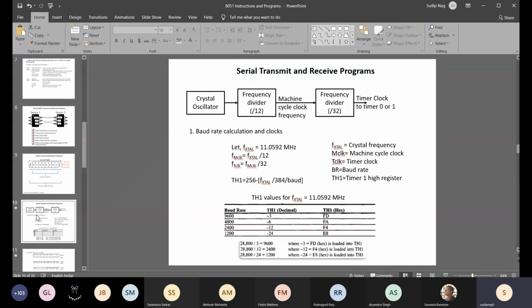So here you can see the crystal oscillator for time base or clock generation is there for any microcontroller, and the oscillator signal is given to some sort of divider. This diagram on the upper side is only for the 8051 microcontroller. Different microcontrollers will have similar diagrams where these numbers and the shape of the diagram will change, but it is very basic and it is for 8051 only.